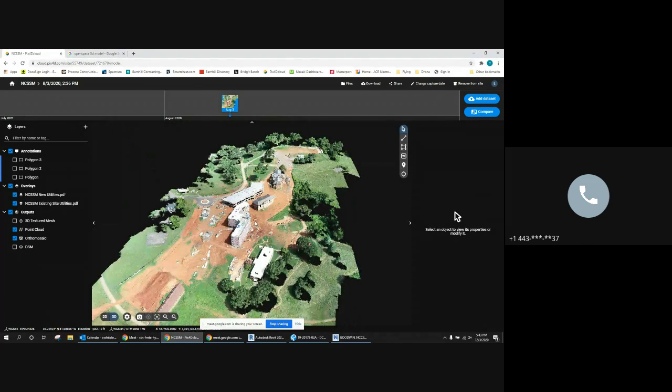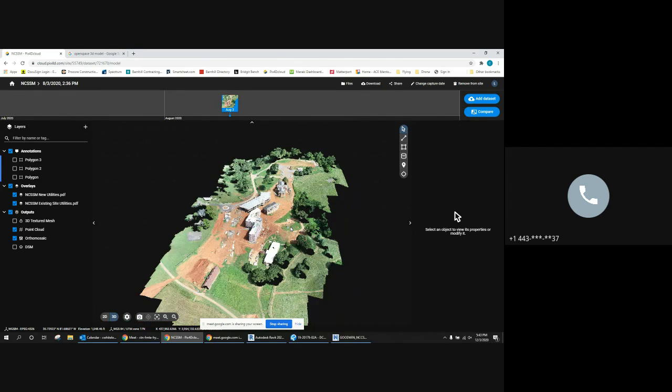One of the things that's changing a lot with big acre sites like this, over 100 acres, is a lot of surveyors are starting to supplement this with what they're doing with total stations. But there's a lot of states and a lot of surveying groups where the accuracy of this for surveying is still ongoing. It's not as accurate as a total station, as a total station is done from the ground, as this is done from the air. So the higher you go, the less accurate it becomes. So it's one of those things. It's kind of a catch-22.